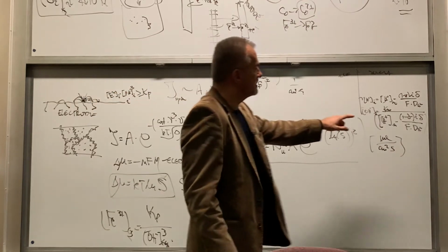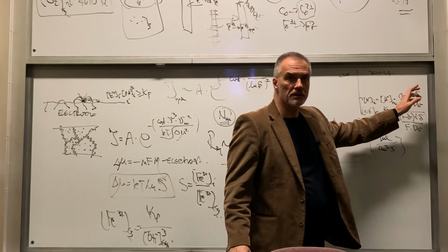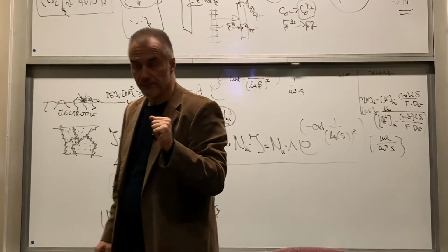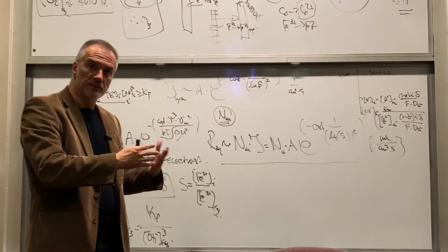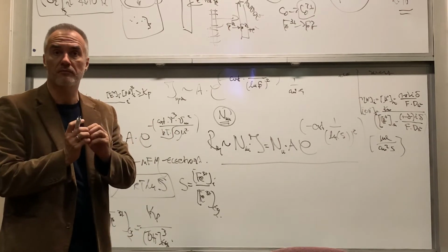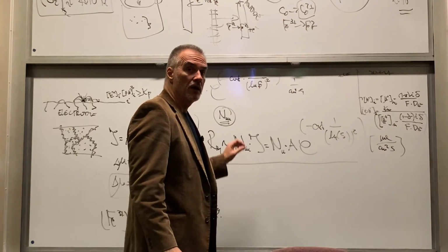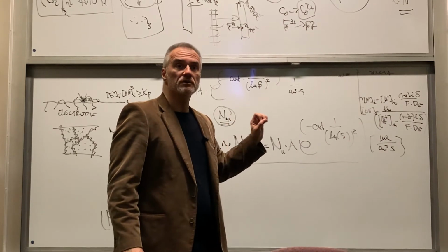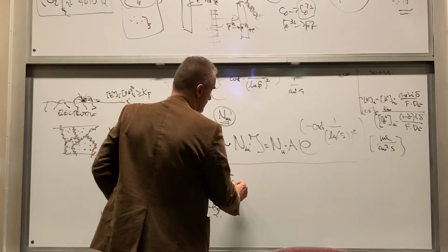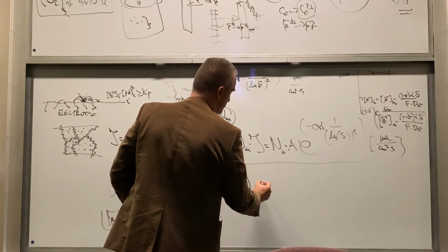For a process that has this gamma, this current density, this diffusion layer thickness, etc. So the next step is very simple. Let's figure out what is the maximum amount of iron 3 plus that I can have at the interface just prior to precipitation. Meaning, what's the iron 3 plus equilibrium at the interface?